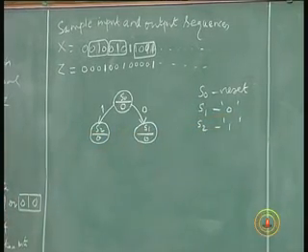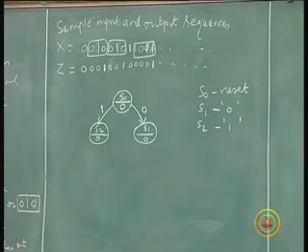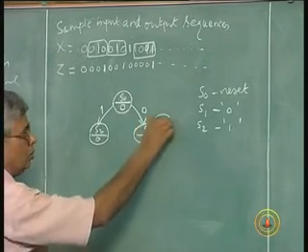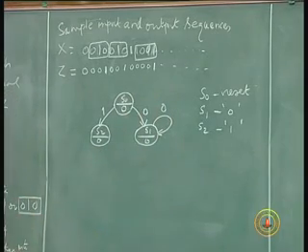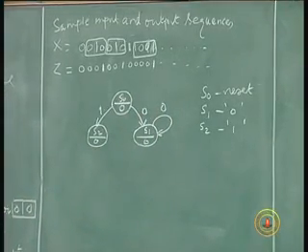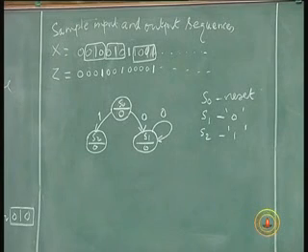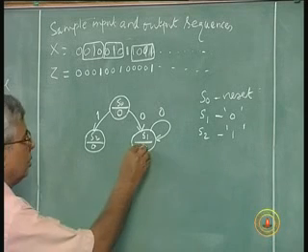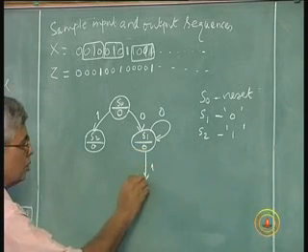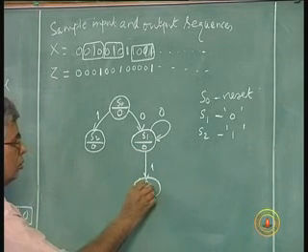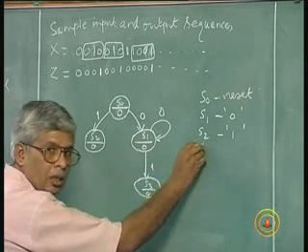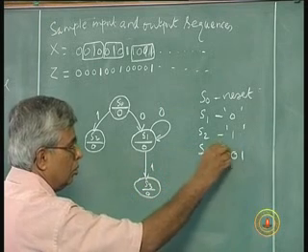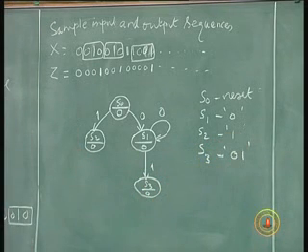Now here it can be a 0 or a 1. If it is a 0, it will continue to be in the state, correct? As long as any number of zeros is there, we stay in S1. Then on a 1, it will go to S3, a 0 state.